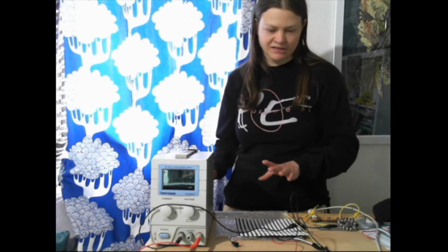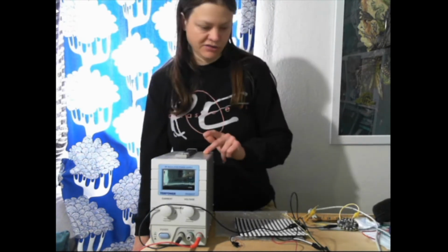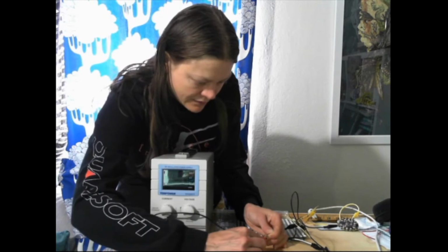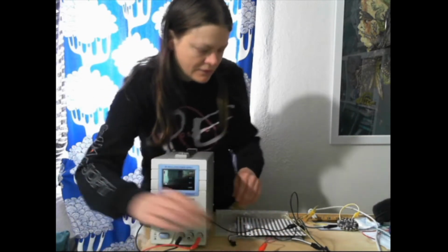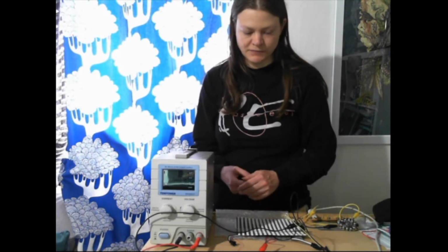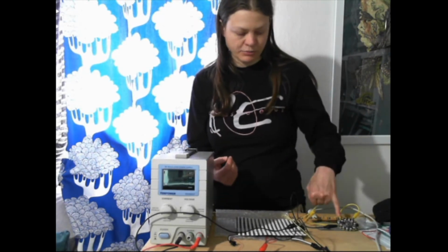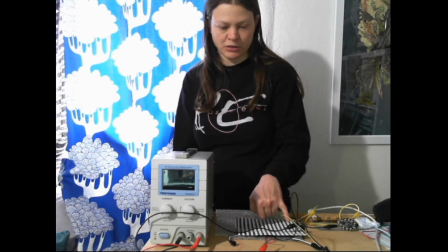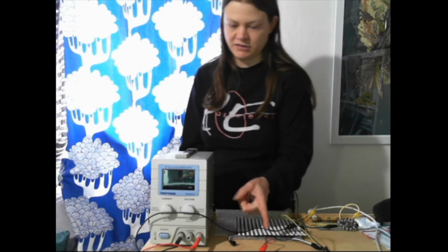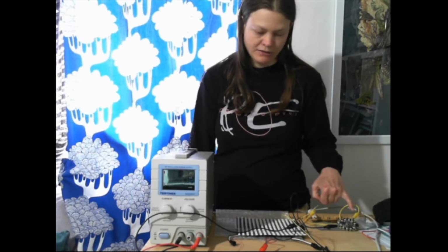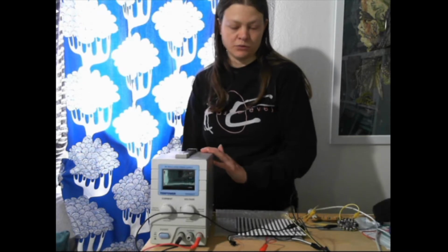Then once you get that, the last step is to connect the power from the power supply to this 5 volt pin on the middle of the matrix, like so. And yeah, at that point, that's the 3 connections. You've got 3 grounds. The one from the Circuit Playground and 2 on the matrix are tied to ground on the power supply. You've got power on your matrix connected to power on the power supply. And you've got pin A1 run into data in on the matrix. Cool, so now we're ready to turn it on.